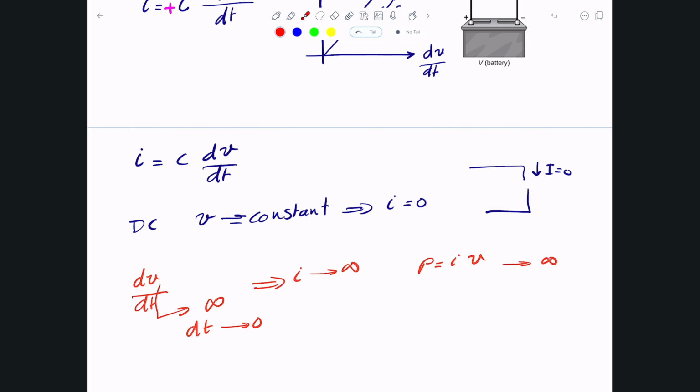But anyway, the key takeaways here are a couple of things. If you put a capacitor in a DC circuit, it acts as an open circuit. And if it's not in a DC circuit, but in a circuit where the voltage is changing, it opposes the change in voltage. It will not allow a drop from 0 to 5 instantaneously. There will be some sort of a delay.